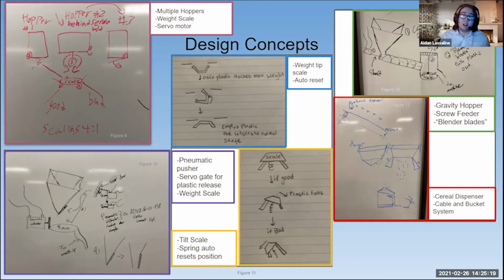The concept for the hopper system is required because it will play a large role in automating our process and will allow the operator to rapidly switch between all 6 types of plastics. The concept for the weighing system plays a vital role in machine cleanliness and operation. If an incorrect amount of plastic enters the heating chamber, we will either have an incomplete mold or we will end up with leftovers still in the nozzle, which would need to be manually cleaned out and put the machine out of operation until cleaning is finished.